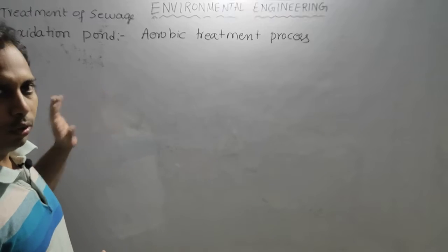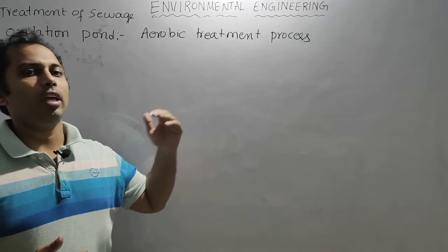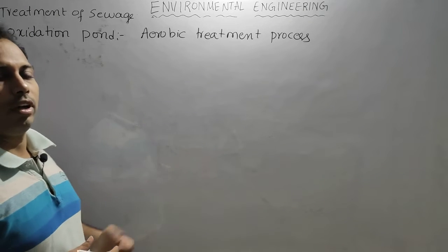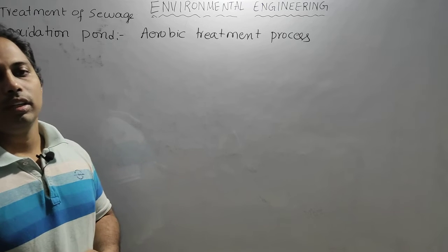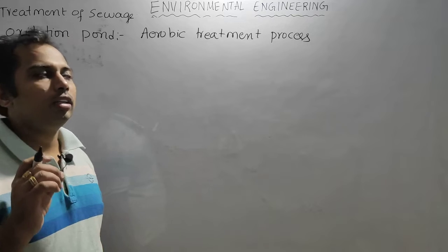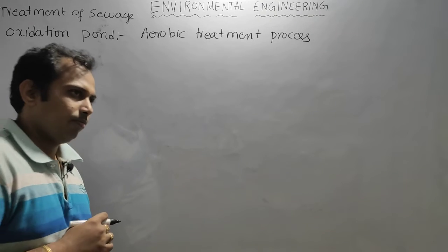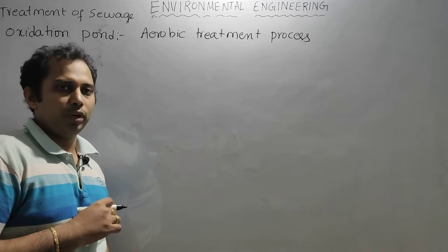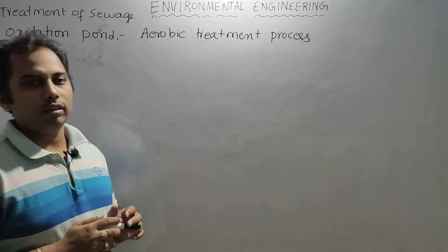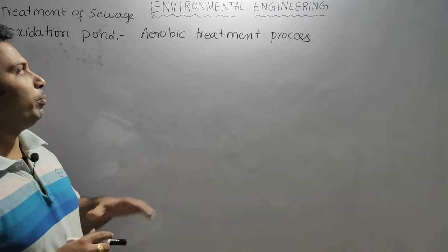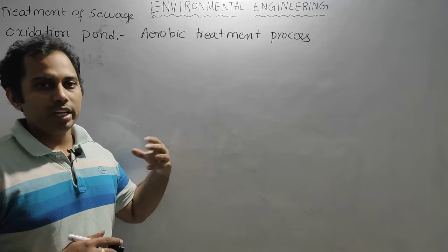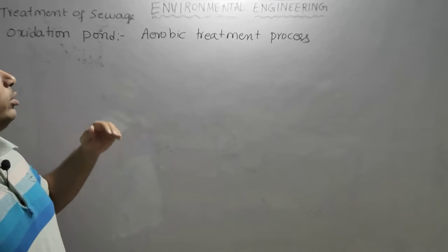It is such a pond only, which may have a very high length and very large width, but it is not a pond for drinking water, it is a pond for decomposition of the sewage. So here is how the decomposition takes place. It is an eco-friendly decomposition system because in this the aerobic microorganisms feed on the organic matter and they will produce end products.